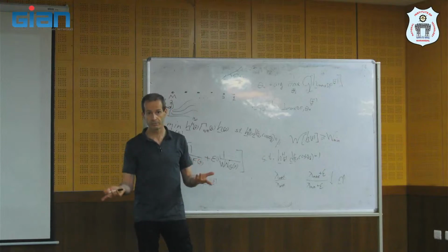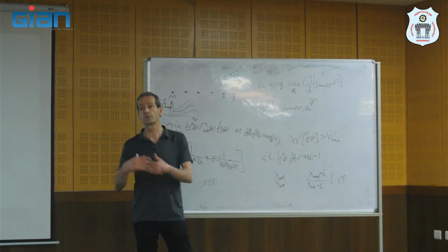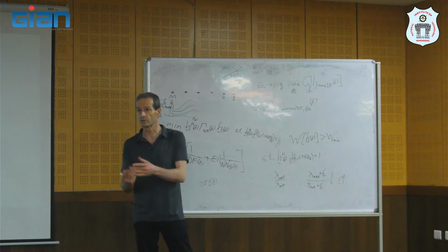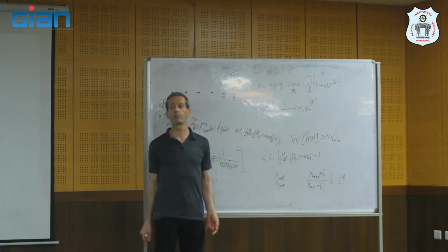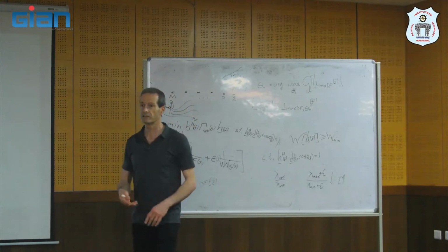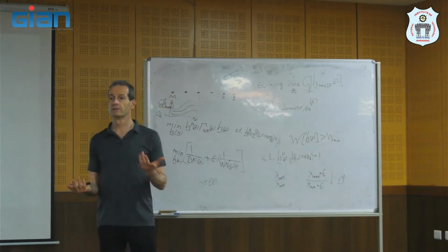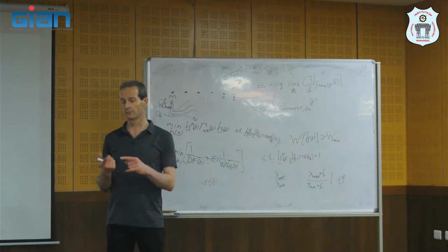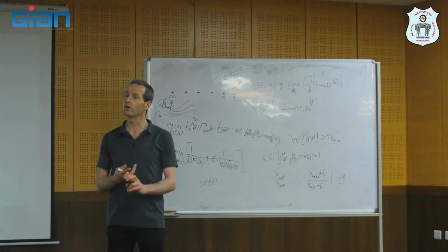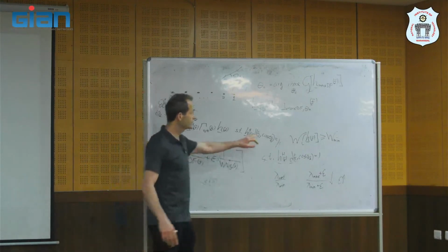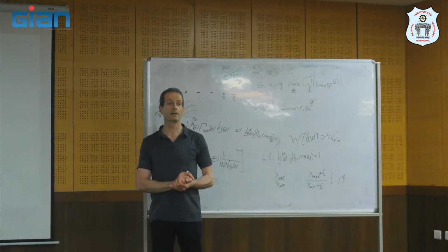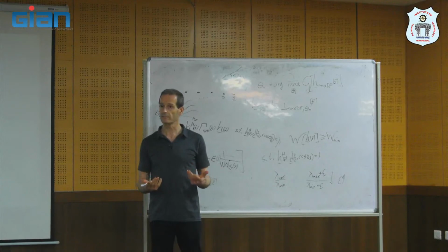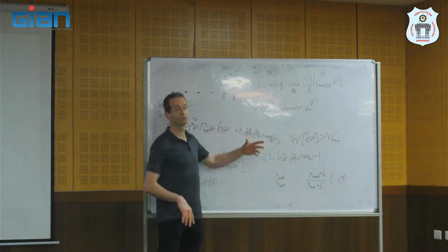When we talk about robust beamforming, you need to know what it is robust with regard to, for example these directions. You can read about robust MVDR, robust LCMV, robust beamformers. Whether robust regarding the noise or regarding the directions, you can modify this optimization with regard to some errors.